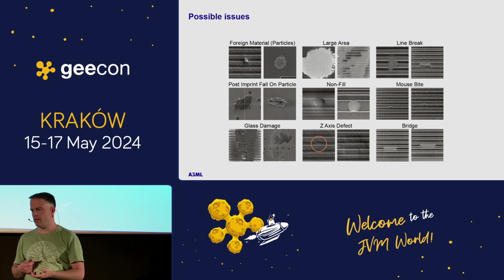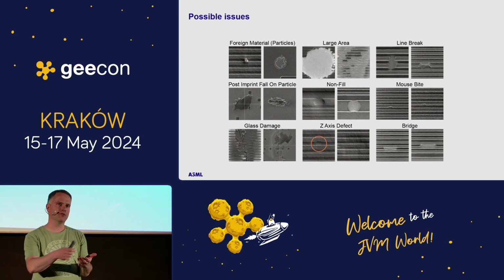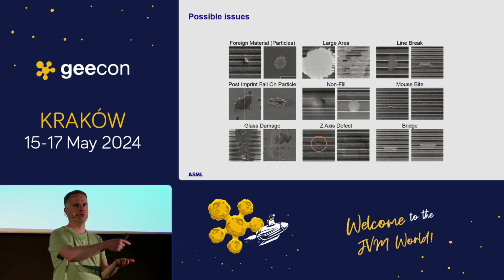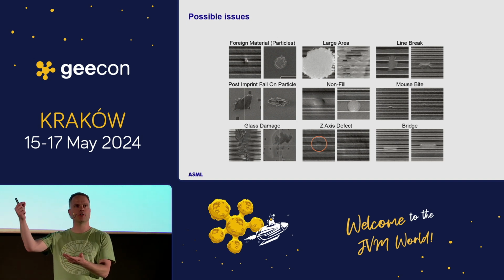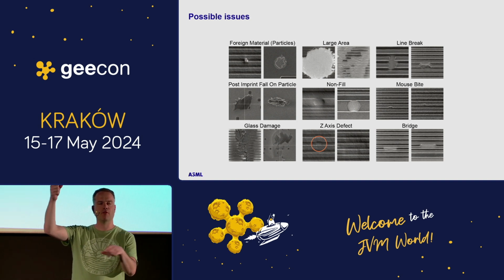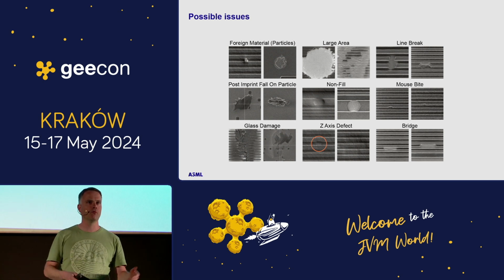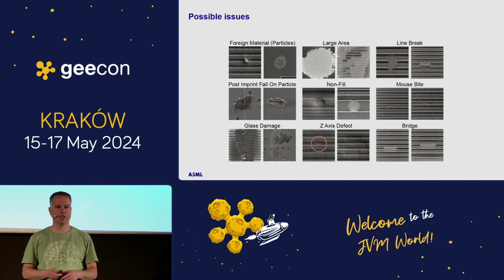So there are many different defects, basically, that you can have. And you can have defects in various places in the process. So let's imagine you have a dust particle on a wafer. Then maybe one chip isn't working, or maybe two or three if it's a big dust particle. But let's imagine you have that same dust particle on a reticle. Then every chip that's being created on that wafer basically will have the same issue. And if you process multiple wafers after each other without detecting that issue, all those wafers basically are useless.